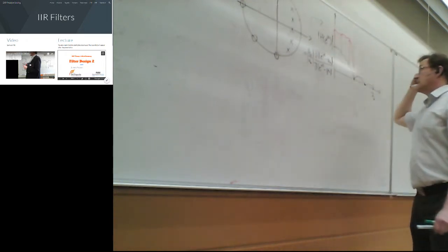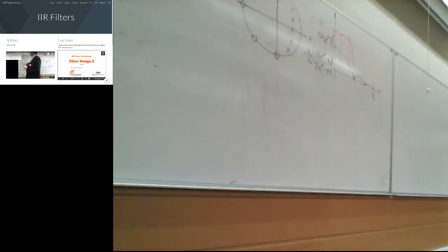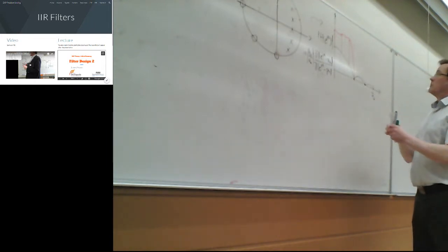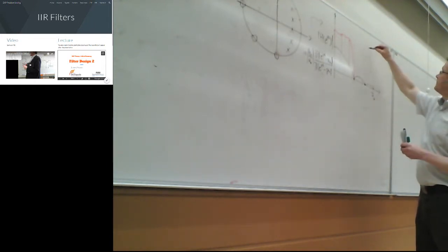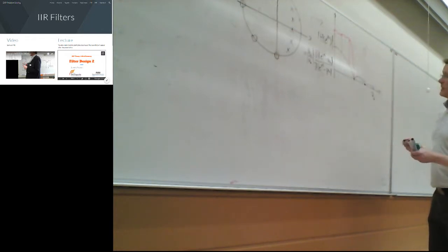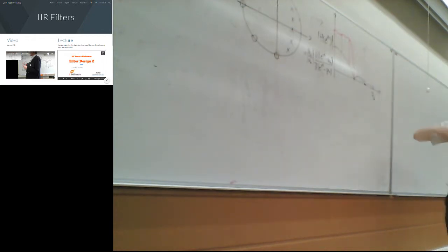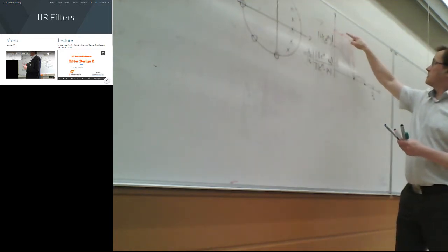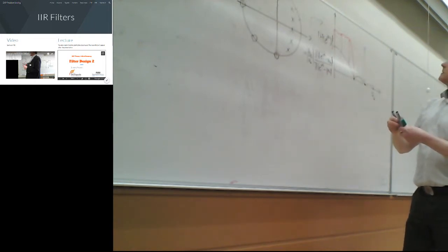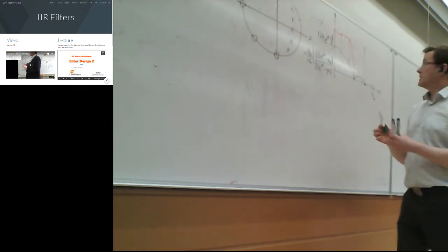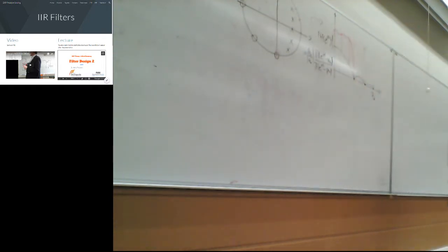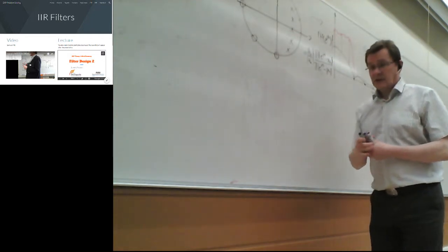And basically that's what usually those poles are for. They will basically give more stopband attenuation, so stopband attenuation gets better, and also you can choose the pole locations so that you will get, say, a relatively flat passband. Okay, so that's one way of looking at it.